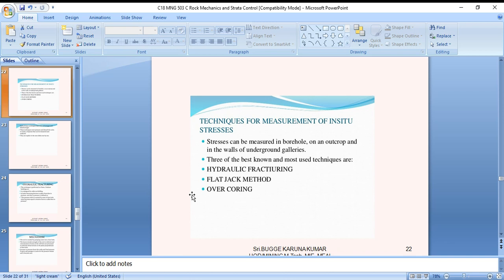Although pressure in the cell is temperature dependent, the variation of temperature in rock is usually small, so that the source of error can be negligible. Except for the possibility of leaks, which are not difficult to prevent, hydraulic cells have good stability over a long period. These are the one type of instruments.